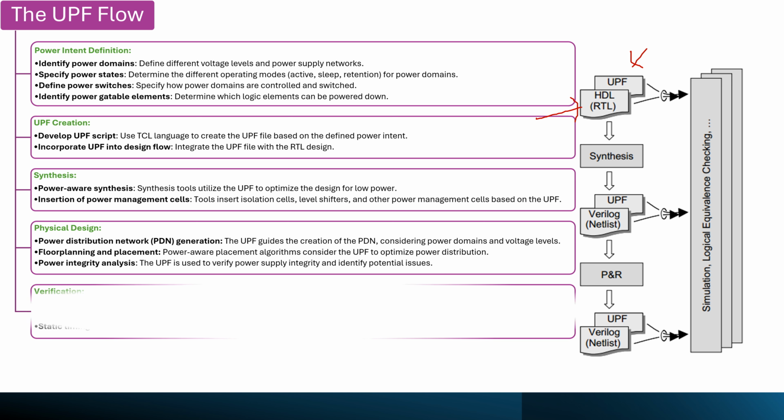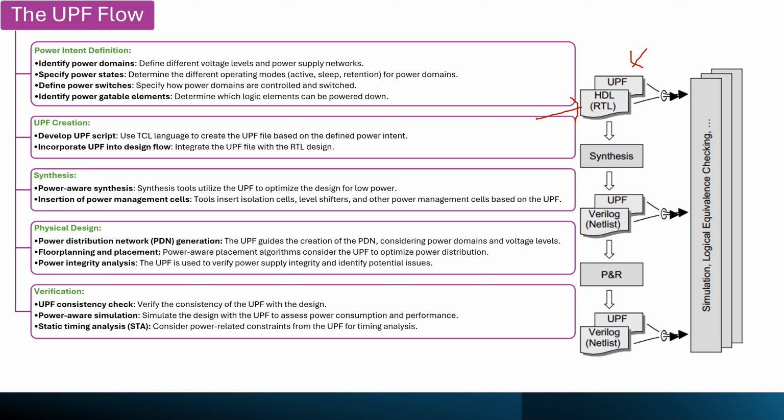Next, once physical design is done, you have to verify it. Typically verification here is either timing verification, static timing analysis, or physical verification, and multiple others also. Let's see how UPF is used here. UPF consistency check: verify the consistency of the UPF with the design. And power aware simulation: you simulate the design with UPF to assess the power consumption and performance. Basically we are talking about post synthesis simulations.